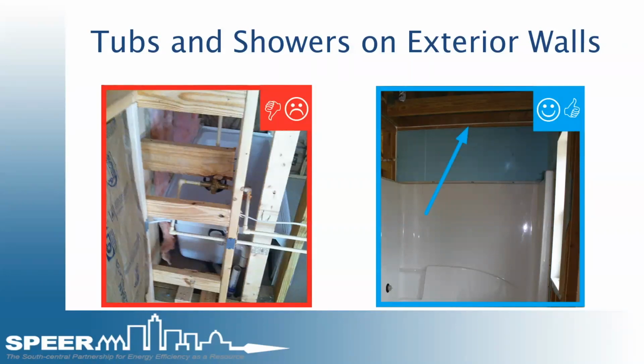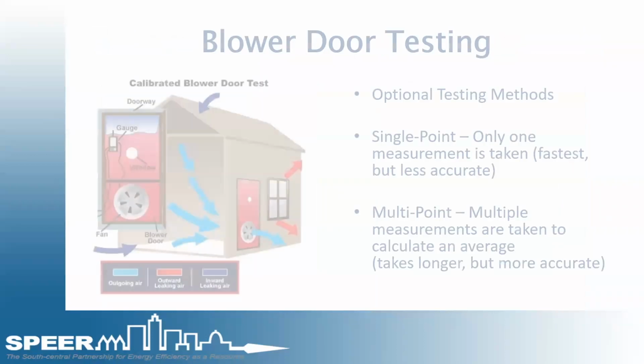That even includes when a tub or shower is installed on the garage wall, you still got to have an air barrier separating the garage wall insulation from the interior side. It has to be air sealed. So doing that pre-tub or shower drop is the best way to handle that, as opposed to trying to do it after the fact. It needs to be blocked from the inside.